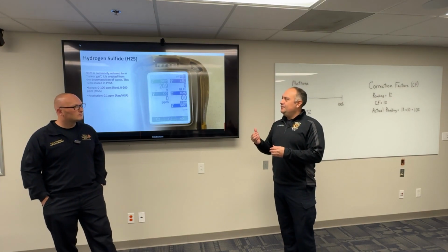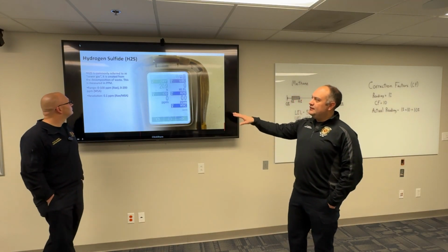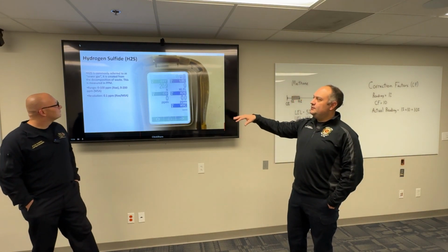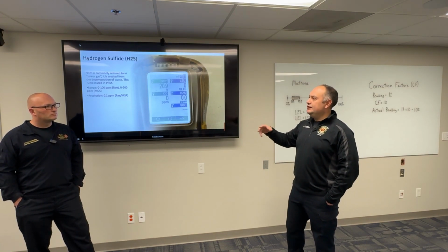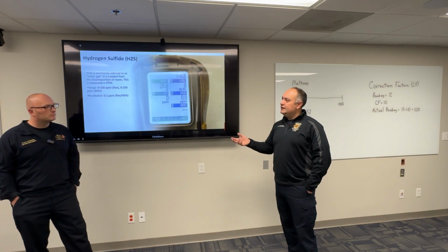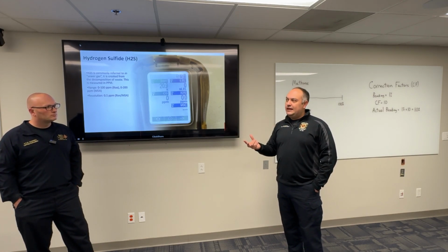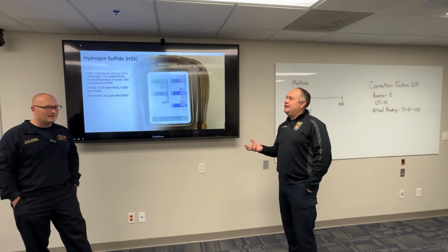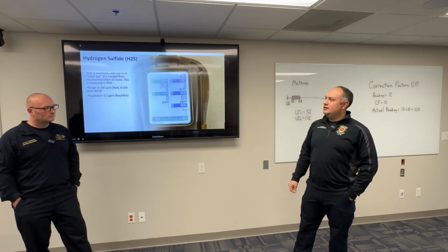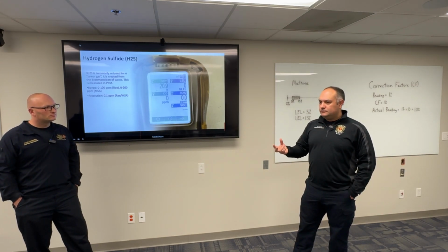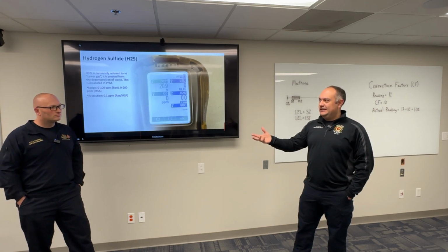Most of the time, if we're talking about our meters, our range is relatively low, 0 to 100 parts per million on the Ray products, and then I looked up MSA, it's 0 to 200. So a little bit more capability, but I wouldn't even know that unless I looked at the manual, like we talked about, right? Resolution, same as some of the other ones, is 0.1 parts per million. So what are some of the calls that you can think of where this could be an issue?